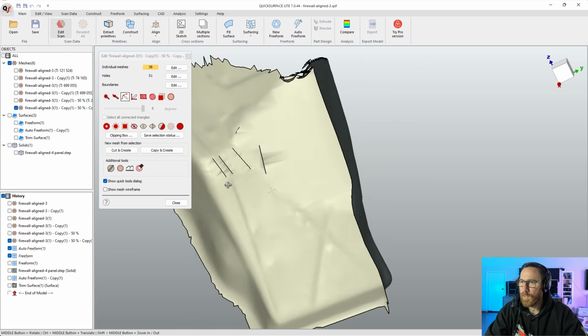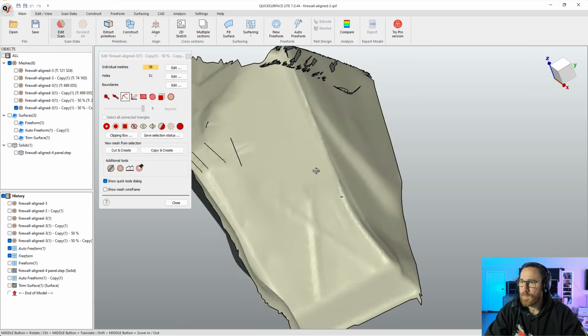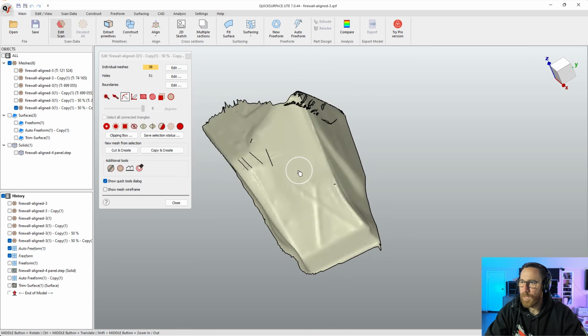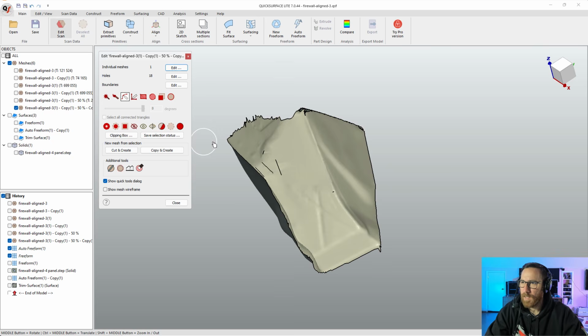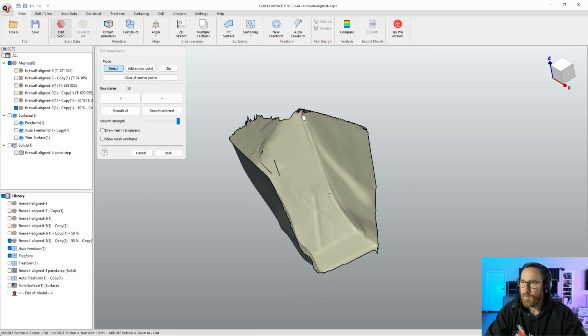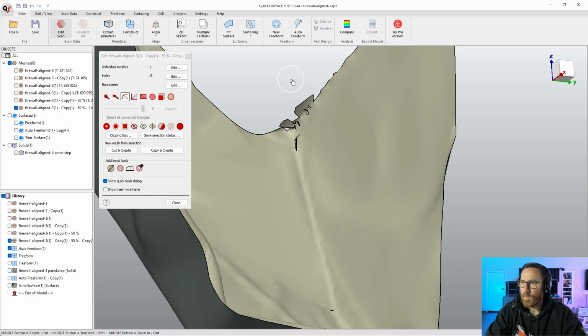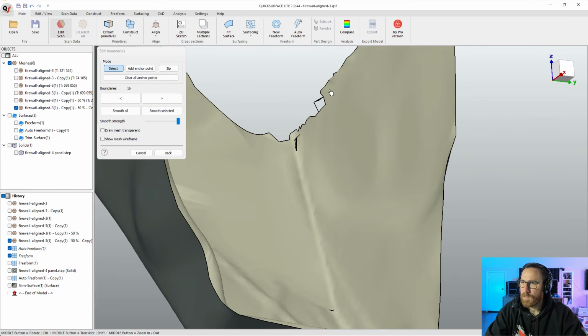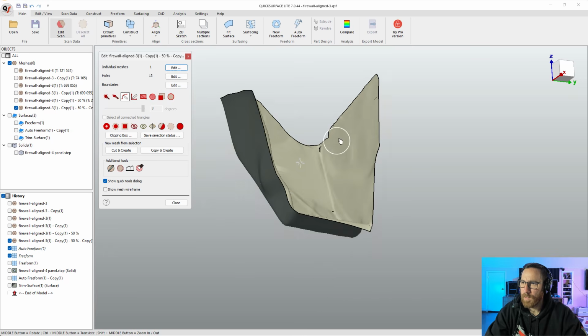All right, so remember when you're trying to do an auto freeform, the cleaner the input, the better. So the boundary needs to be clean. We've got to get rid of all these little extra pieces. So once again, select that, keep only that. Boundary, want to clean up. And there's a little bit of stuff going on there. So maybe delete that. I'll go back to the boundary and try to clean it up. And then again, keep just the one body.